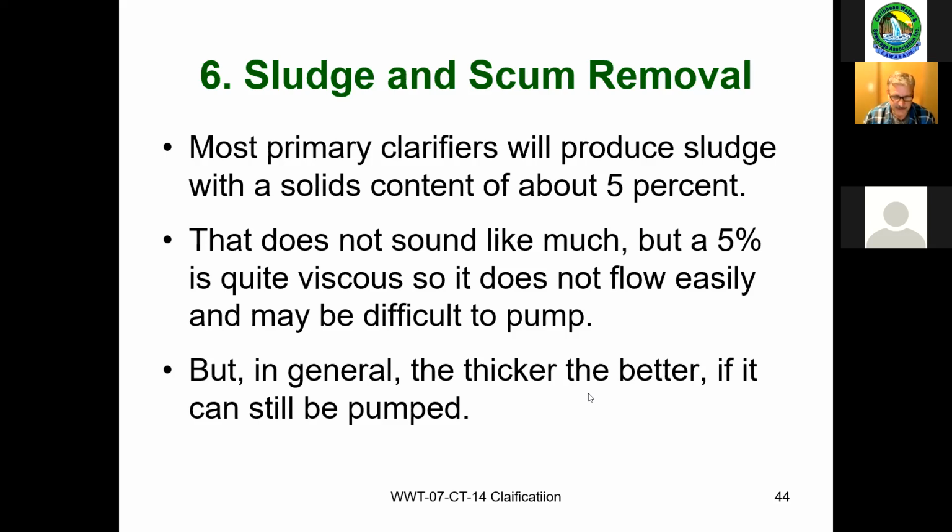If you're taking it for drying, that can be a tricky situation sometimes as well. You don't want it so thick that you can't pump it, but you don't want it so thin that you're just putting water in your drying beds. So that needs to be maintained and analyzed as well.